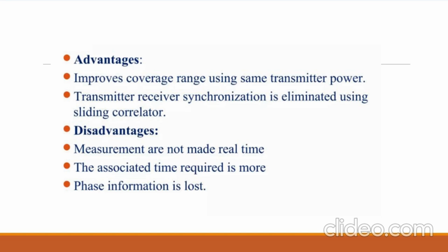And the drawbacks are real-time measurement is not mostly possible, and the time requirement is more, and it involves complex PN sequence generation and multiplication, and so on. Also the phase information is not retrieved because of the use of envelope detector.